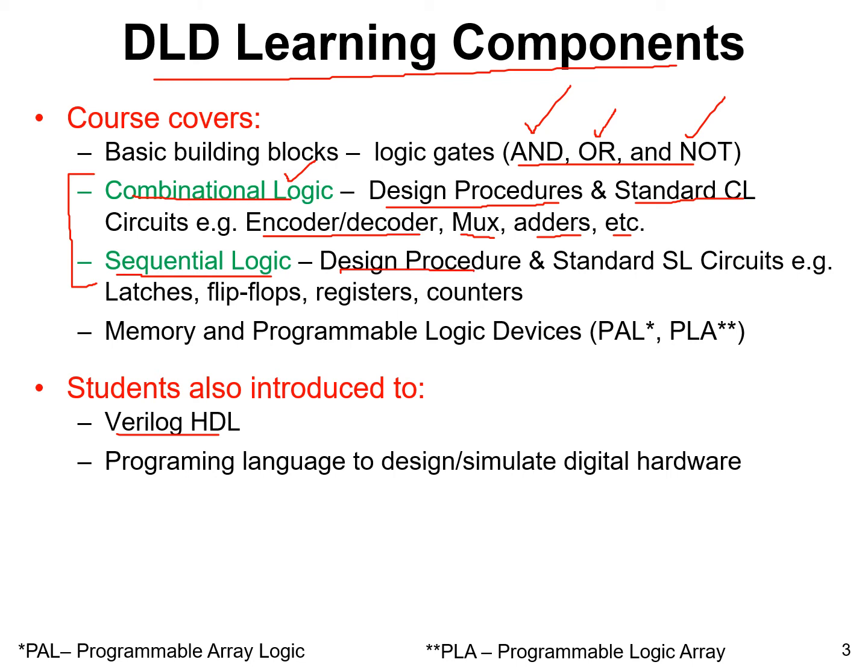And in the sequential circuit, we will use another design tool in order to design the sequential logic circuit, and that design tool is called the state machine approach. Through the application of the state machine approach, we may design some standard sequential logic circuits. The examples are the latches, the flip-flops, the registers, and counters.